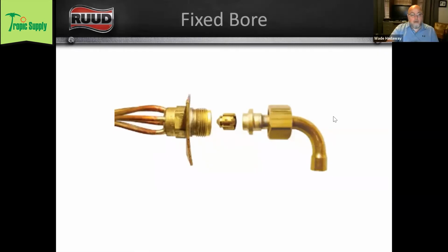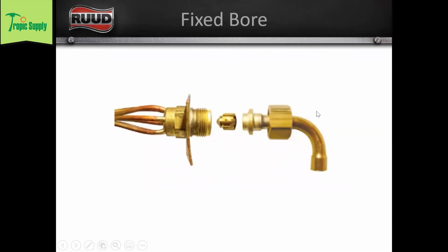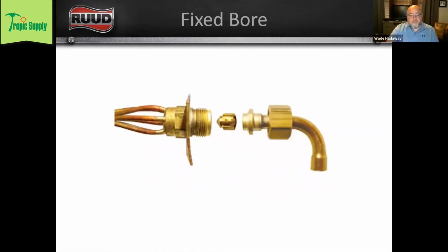Another guy: Is the scale still between 5 and 20 degrees for the superheat? So I guess it depends, right? If we're not charging by superheat, I was always taught, just same as David, 8 to 12 degrees of superheat is what we're looking for. But really, we just want to see, coming out of our evaporator coil, do we know that we're 100% vapor, right?